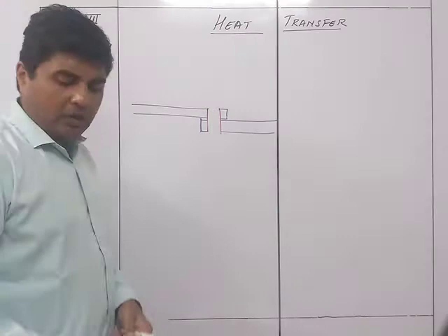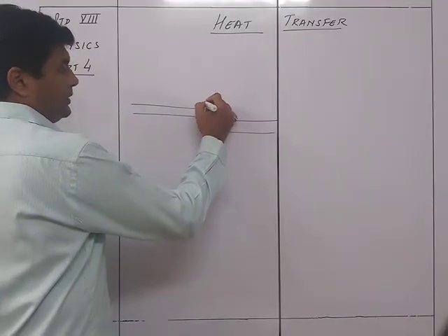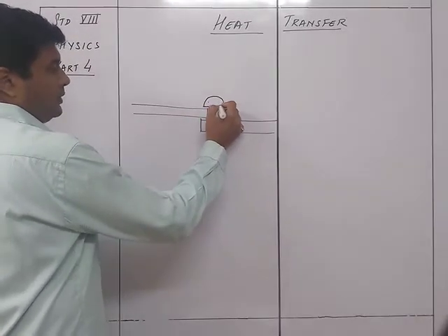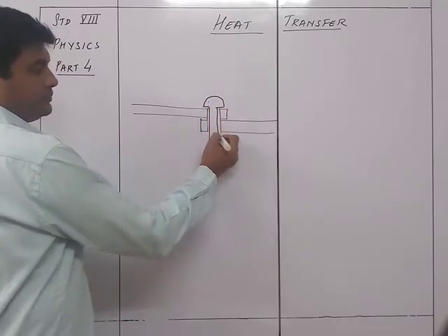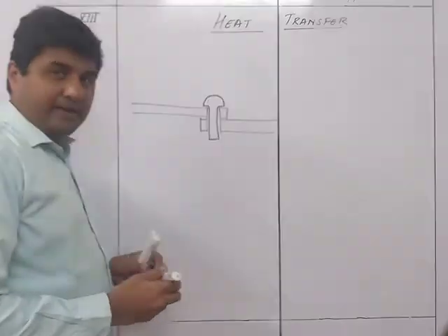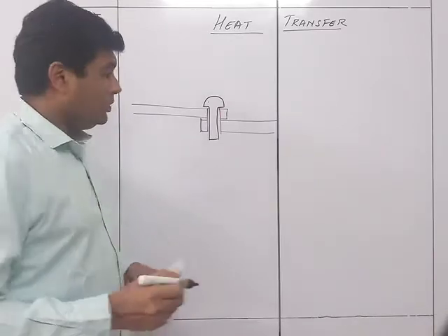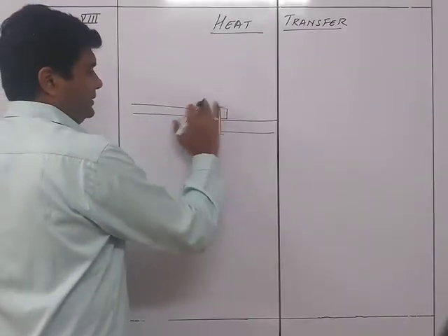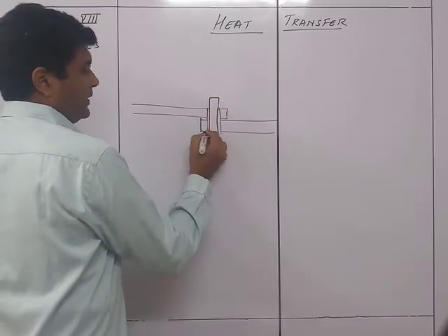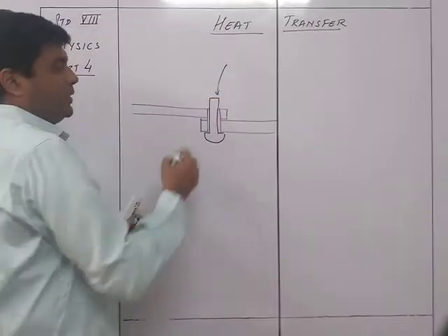And inside this hole, you are going to place a rivet which is of this shape. Okay, this is the shape of the rivet. So what you are going to do is place it inside and then start hammering it. In fact, you are going to place it upside down, like this with the head over here. So this is how you are going to place it, and then you are going to start hammering over here.